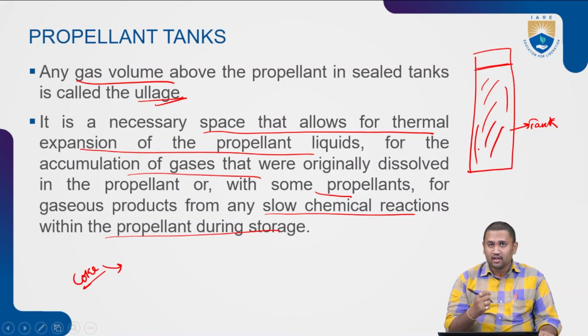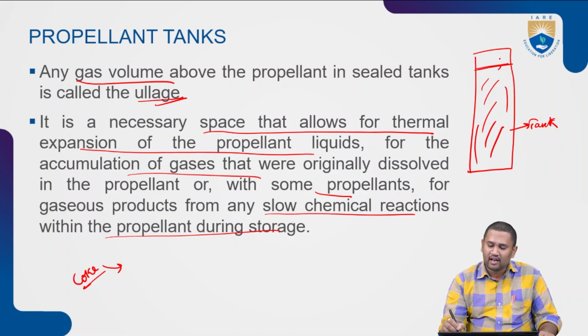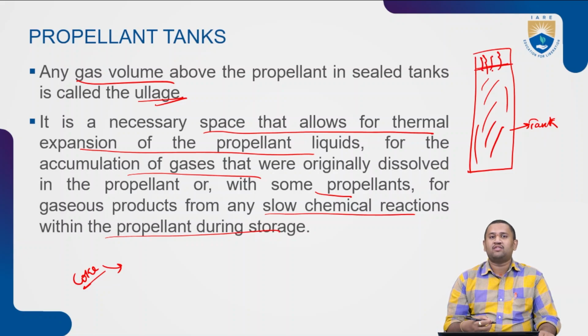Because in order to cope with the evaporating gases coming out from the tank, or if any reaction does take place, or any thermal expansion of the liquids happens, that particular area is left out for the fuel or the oxidizer to expand itself.